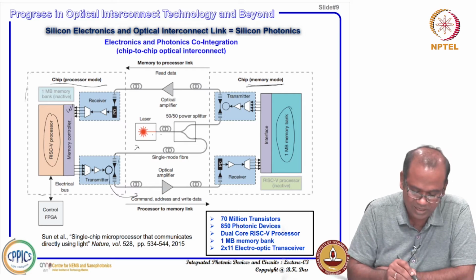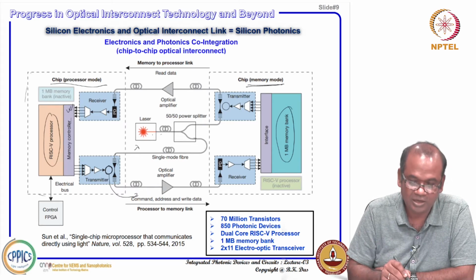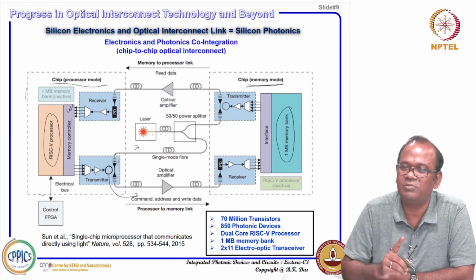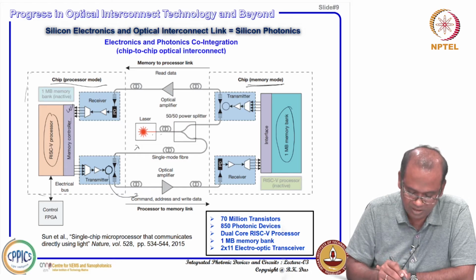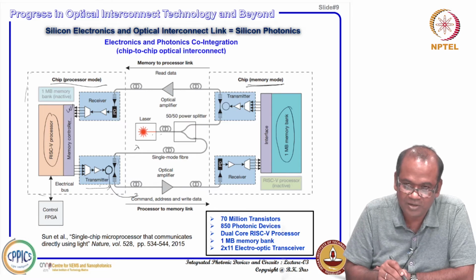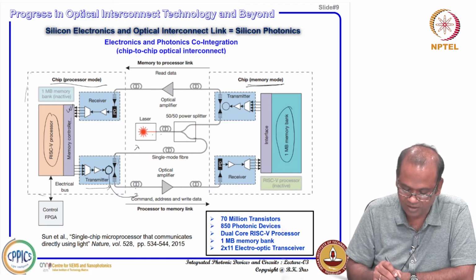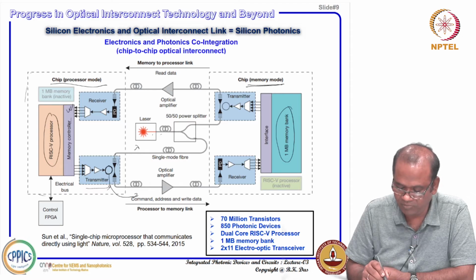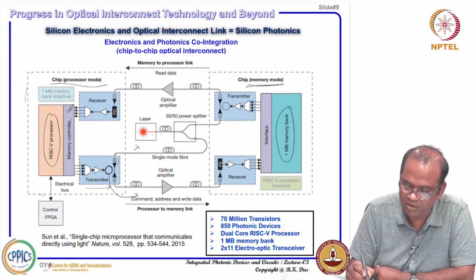So, any digital data coming into this driver and feeding into the ring, it is some kind of modulator, a ring modulator I would say. That means electrical to optical conversion is happening, then modulated light will be coming. So, data will be encoded here, okay, that is actually called the transmitter. So, laser light coming, and then you use a fiber optical amplifier, and then you have a receiver photodetector, deserializing again, an interface here, and from here again you have a transmitter.